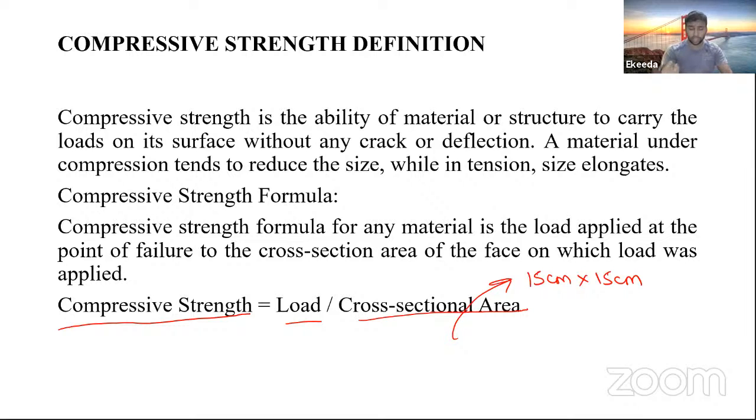Now, I will give you a brief idea about the RMC plant. At each and every RMC plant, there is one portion in which the concrete is prepared and one portion in which the laboratory is constructed. Now, in the laboratory, before producing any batch of concrete, they take a sample of that concrete and do the basic tests, that is the slump cone test as well as the compressive strength test.